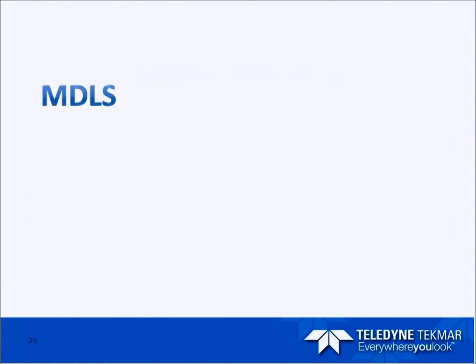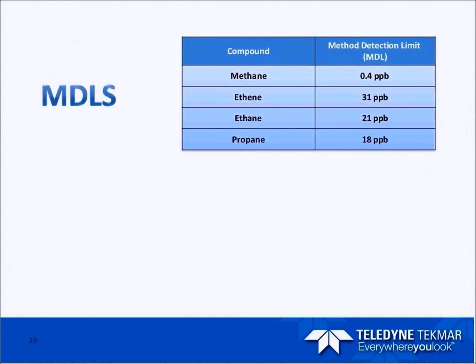Okay, so we have MDLs. As you can see, they look really good. The methane is really low. Since we're optimized for methane, it's really reproducible. At the low end, there's no background or anything. It looks great. And all the other ones, ethene through propane, are well below your calibration ranges. So everything looks really good with our MDLs.